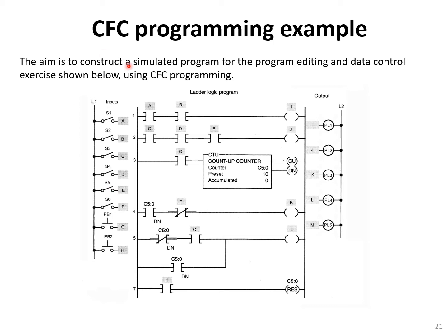Okay, now let's go to a more complex example in the CFC environment. The aim is to construct a simulated program for the program editing and data control exercise shown below using CFC programming. Okay, so we have the ladder logic program here. You see lots of inputs and outputs, but the logic is, I think, quite easy, except for this counter op block. So you see that we have reset, negated, and the normal contact and coils.